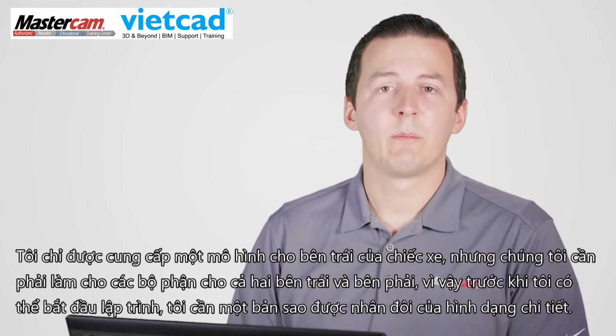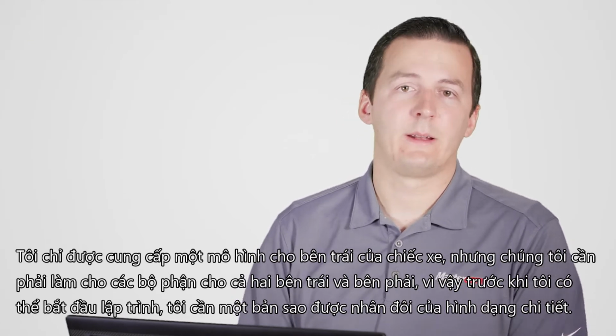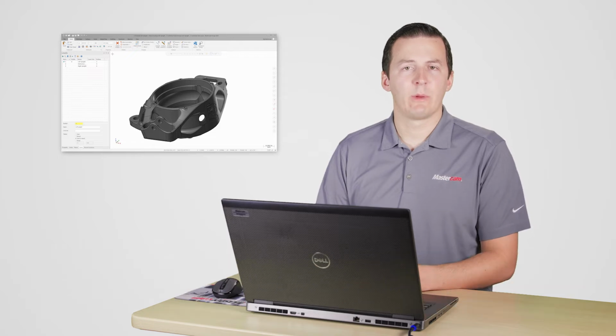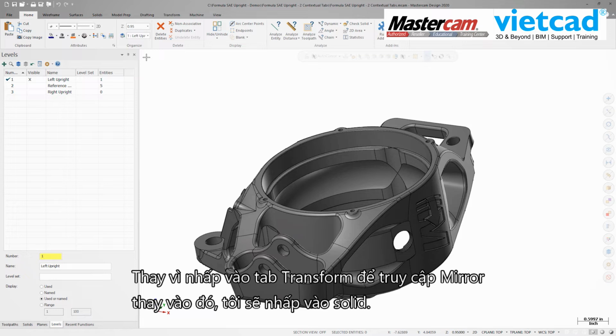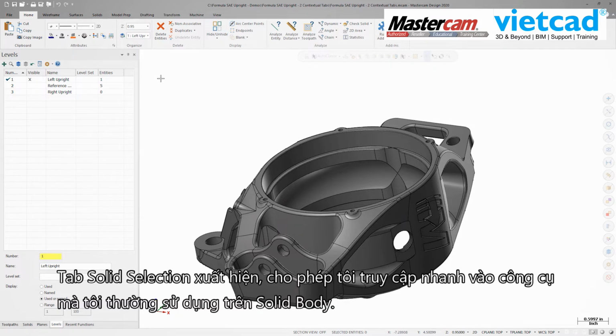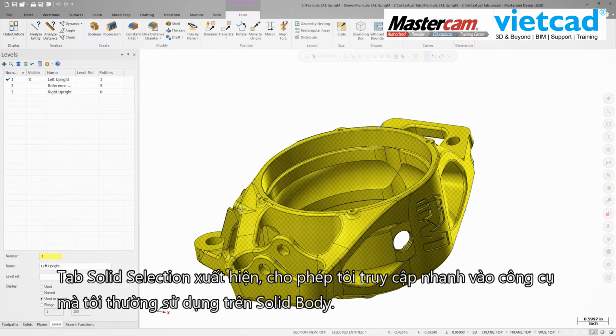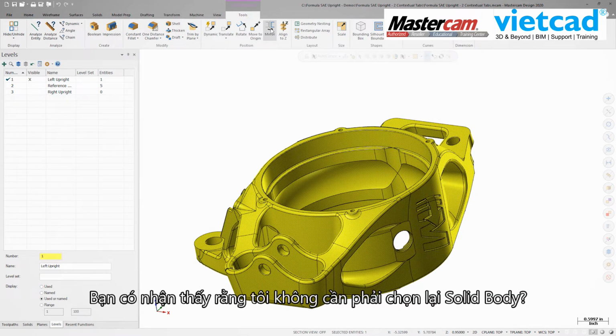I was only provided with a model for the left side of the car, but we need to make parts for both the left and the right side. So before I can start programming, I need a mirrored copy of the part geometry. Instead of clicking on the Transform tab to access the mirror command, I'm going to click on the solid body instead. The Solid Selection tab appears, giving me quick access to tools that I would commonly use on a solid body. From here, I'll open the mirror command.